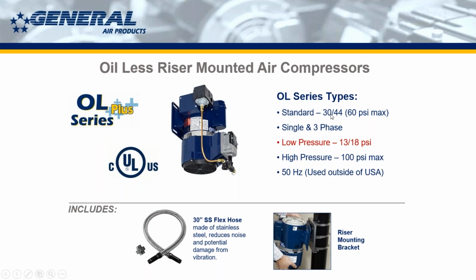If you ever feel like you need a tighter differential, let's say because you need a low pressure unit, 13 to 18, that can't go any smaller than that 5 PSI differential, okay? So that's really important to understand.